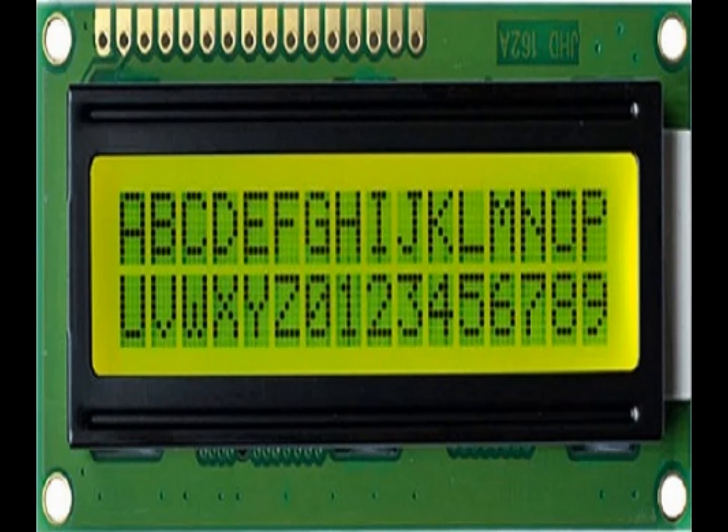Next is the E pin, which initiates the writing process to the registers, or the next 8 data pins from D0 to D7. Basically, through this pin, we are sending the 8 bits of data when we are writing to the other pins on the LCD board. For example, if we want to see the letter uppercase A on the display, we will send 0100 0001 to the registers according to the ASCII table. The last 2 pins, A and K, or anode and cathode, are for the LED backlight.